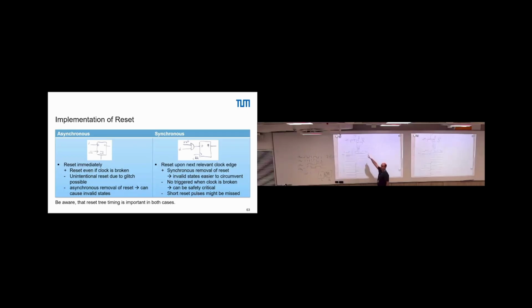We can try to improve our timing there, to make this very similar, but even if we push as hard as we can, we will not have it perfect. So this case virtually always can happen. So what's the problem? We have effectively no control over the clock input here. So we have possibly invalid states.